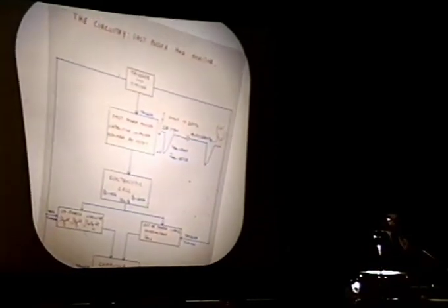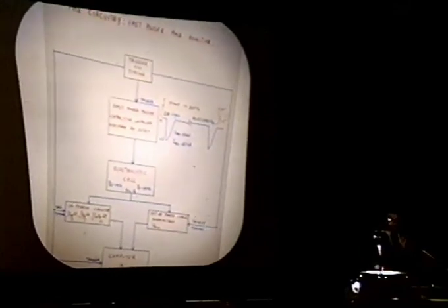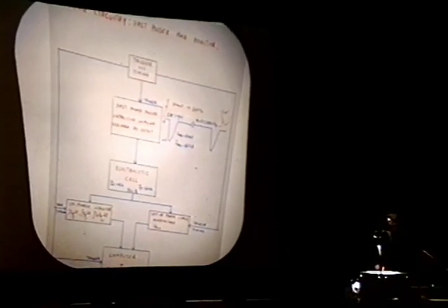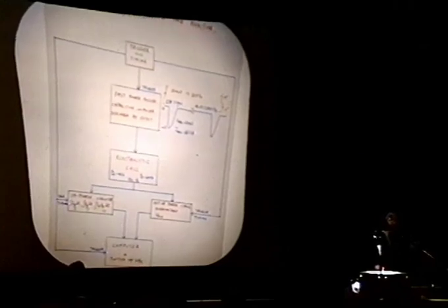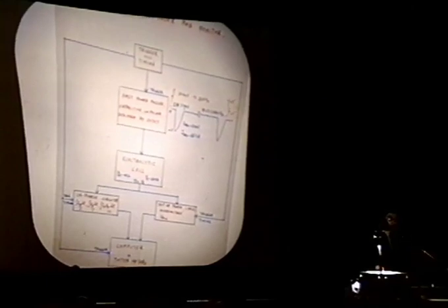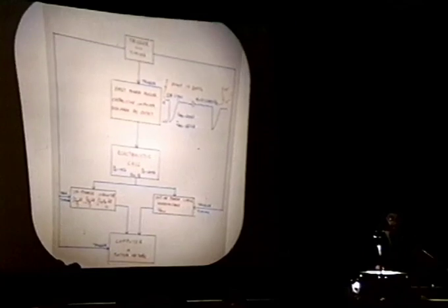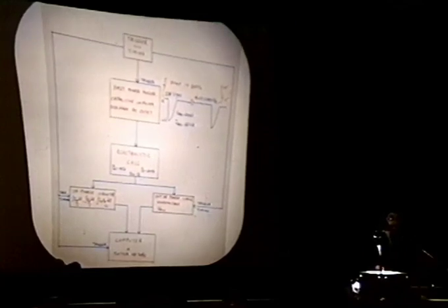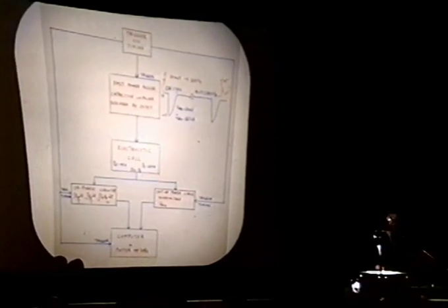We made a very powerful pulse trigger, and we get the peak pulse. So we acquire the mean current and mean voltage, and we make online, by a fast multiplier, the multiplication between peak current and peak voltage for the power.